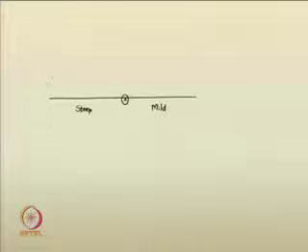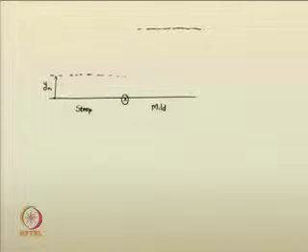The normal depth in the steep channel is given by y n 1. The normal depth in the mild channel, let us consider this as y n 2. You also have some critical flow in between these two normal depths, that you are also aware of. So, how does the change occur from this junction point, whether the jump occurs on the left side or on the right side. Consider, or you just replot them again.